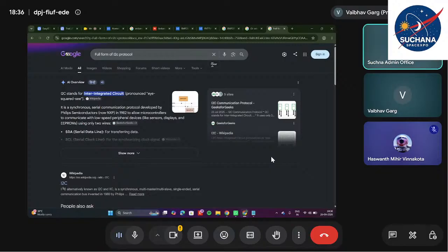Other than these two addresses, no other address will be available for the same company's sensor. So now both have different addresses, and both can communicate with the microcontroller. Is that clear? Yes. So let's say now I have five BMP280s and a single microcontroller. I want all five BMP280s to work. How will you do that?